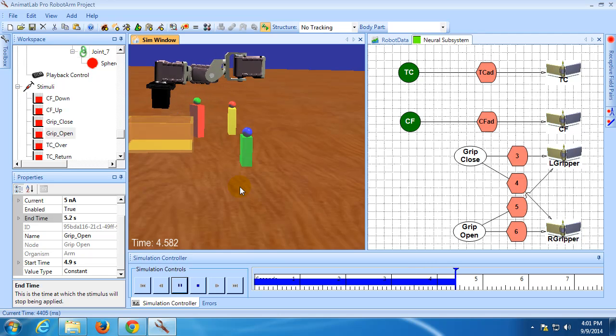Uh-oh. This time when we run the simulation, the arm makes the movements that we want, but when it tries to pick the ball up, it's not able to keep a grip on it. This actually demonstrates a major problem that I ran into when trying to get the gripper to work in the simulation. No matter how hard I had it squeeze on an object, or how high I turned up the friction, the item it was gripping would just slowly slip out of the grippers.